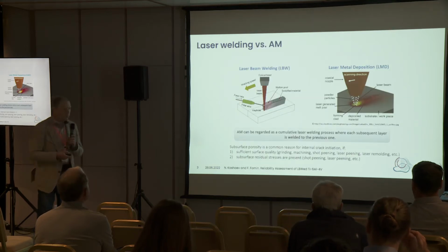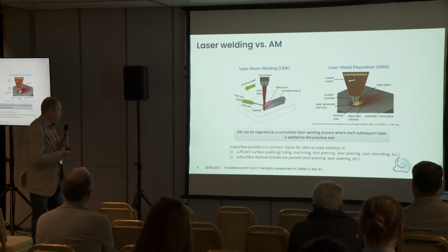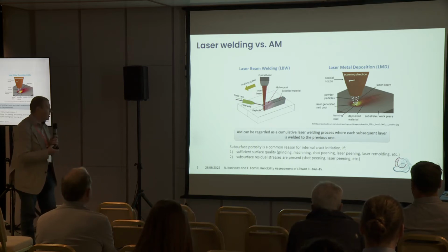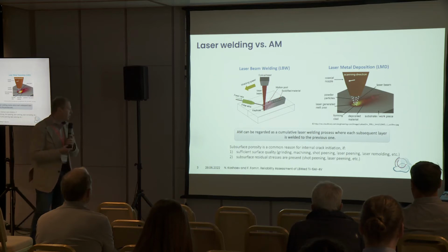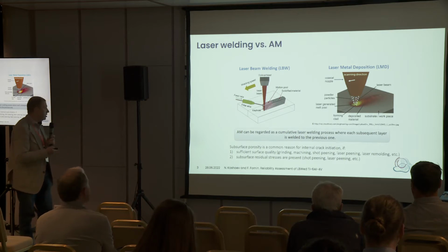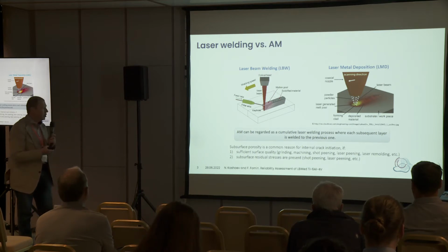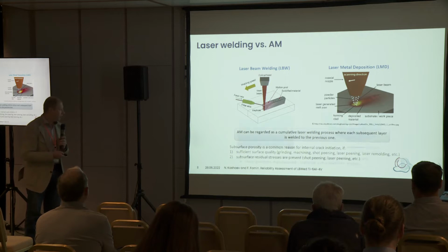And if we compare the laser welding process with additive manufacturing processes using fusion, we will find a lot of similarities. Subsurface porosity is a common reason for internal crack initiation if sufficient surface quality, by grinding, machining, shot peening, laser peening or laser remelting, is applied, and subsurface residual stresses are present. Additive manufacturing can be regarded as a cumulative laser welding process where each subsequent layer is welded to the previous one.